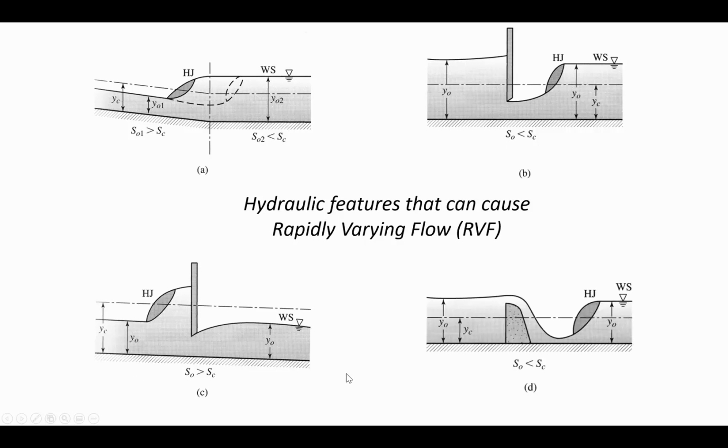And finally, we talked about spillways already. The flow that's coming down the front face of a spillway, dropping from the top of a dam back down to the river below, gathers quite a lot of velocity. It picks up enough velocity that it's moving supercritical and the water has to go through a hydraulic jump. We're going to watch a video in a moment that talks about this, and about how the water is moving so fast that it can damage the stream. It has a lot of velocity, and there's energy there that could cause scour.